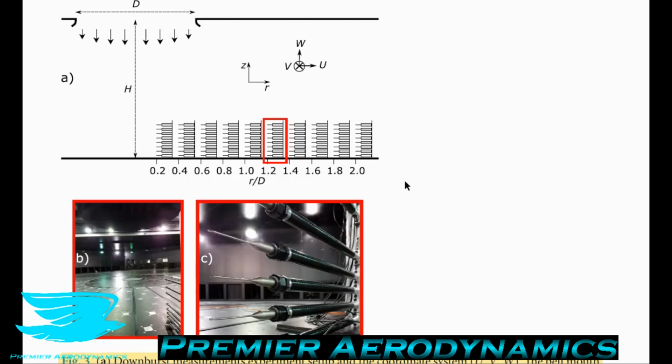If you want to have more holes, typically the probe gets bigger, because you just need to accommodate these holes, and that means that you disturb the flow more. And also the point that you're measuring is no longer a discrete point. You're now measuring over an actual area or a volume. So the bigger the probe, the bigger the area that you're measuring over. So you can't really say that the flow at this point is whatever velocity, you have to say the flow in this area is this velocity, generally speaking. So there's some error occurring there. So having a smaller probe is very beneficial from that point of view.